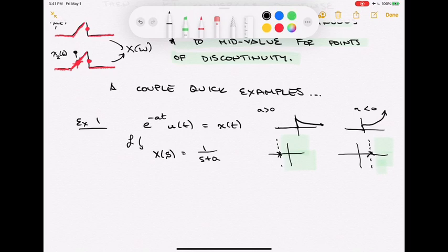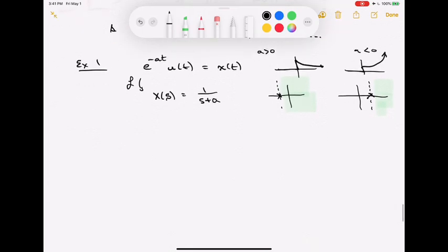We'd like to look at this same signal, right, but we'd like to do it Fourier style. So we'd like to find its Fourier transform. It's an aperiodic continuous signal, so it should have a spectral density, some spectrum, some X of omega. What is X of omega equal to? It's an integral, right? Minus infinity to infinity of my signal x of t times e to the minus j omega t dt.